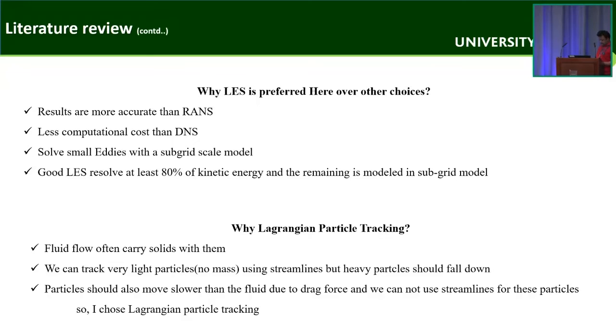RANS is also used when bulk quantities are looked for, although evidence recommends that RANS models are incapable of demonstrating crucial turbulent quantities in unsteady cases. So LES is able to resolve smaller scales better than RANS. Furthermore, in the case of unsteady simulations, LES captures dynamic turbulence, which helps to understand particle and fluid flow patterns in complex geometries. So basically I chose the LES model here.